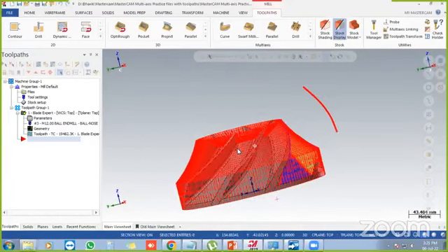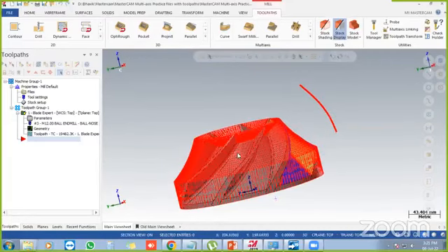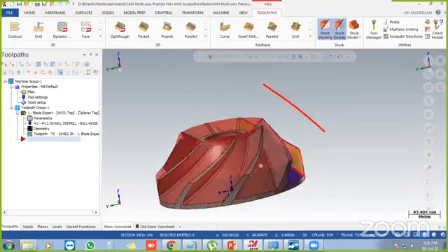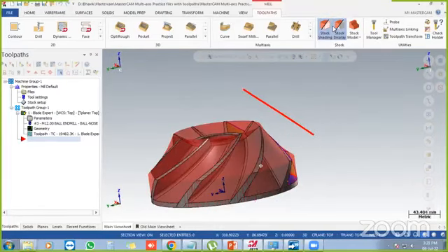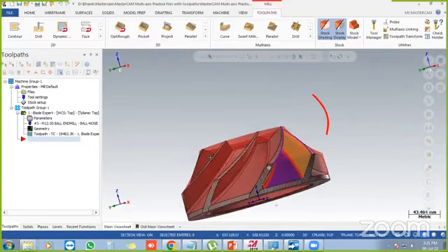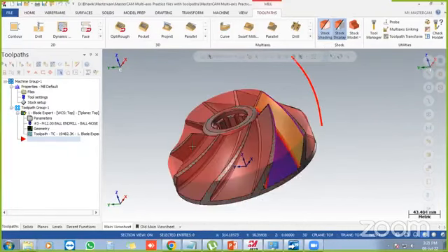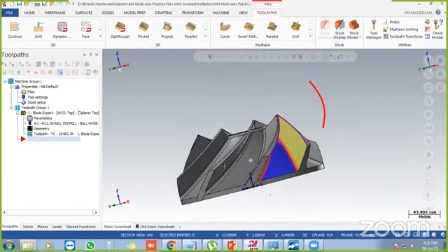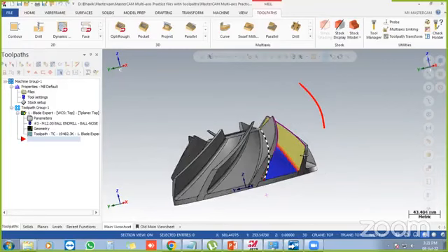So you just need to make a CAD model and then export it to Mastercam, specify the blank shape, and then generate the toolpath with various details. So how will it work? This can only be done in a multi-axis machine, which has a configuration different from 3-axis machines.